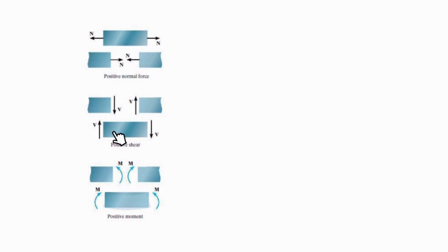For the shear, it's like going from left to the top and getting down. This is the positive. We set this positive direction for the vertical forces or the shear forces, meaning that as long as I cut and I have a force like this on the right side of the surface which is cut, as soon as it is downward, we name this positive.